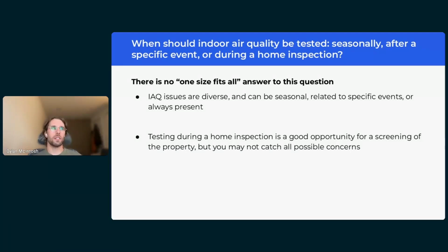I've had a lot of cases where someone's indoor relative humidity might be very, very low, and that causes irritation to them. We might not think of temperature and humidity as an air quality issue, and it kind of is in a way. It's a comfort issue. Same with a furnace that's not maintained properly and may not be having very complete combustion. You could have carbon monoxide issues in the winter that you don't have in the summer.